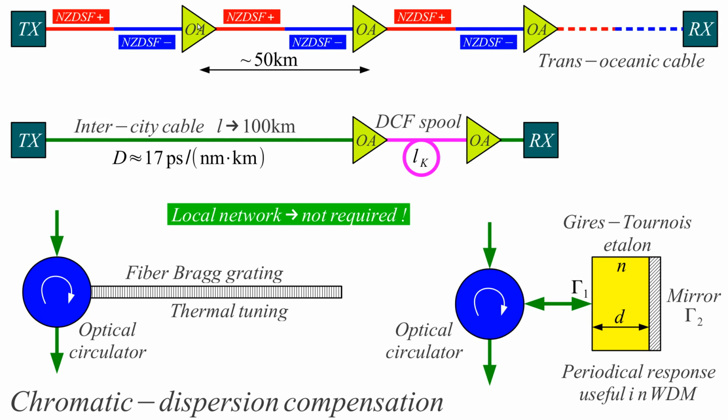A transoceanic cable is designed as an analog transmission line, not to have any signal processing on the bottom of the ocean. With a spacing around 50 kilometers, at a transoceanic length of 5,000 kilometers, we may have 100 optical amplifiers, and these are completely analog amplifiers.